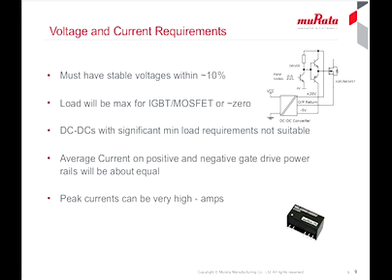We've sized the DC-DC for power, but what about voltage and current? If you look at IGBT or MOSFET data sheets, you can see that there is quite a wide tolerance on the gate threshold voltage for switching, and the margin between this value and the absolute maximum. However, a system designer will choose the voltages that give the very best efficiency from the device and the best EMC performance.